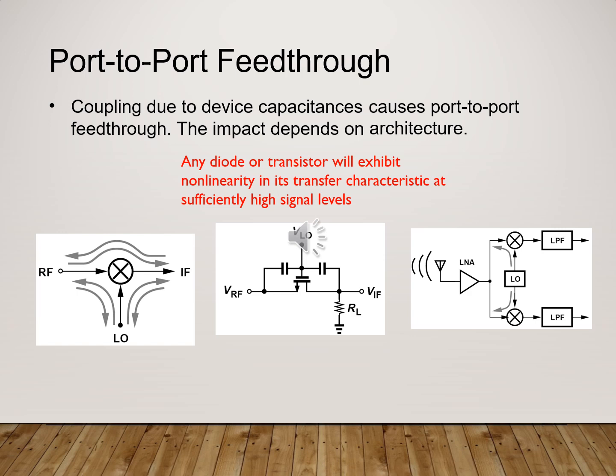The output of a nonlinear device may contain DC terms, RF and local oscillator feed-through, and terms at all harmonics of the RF and local frequencies. Only the second order product term gives the desired output. Now we need some isolation between these ports. Isolation is a measure of the leakage or feed-through from one port to another.